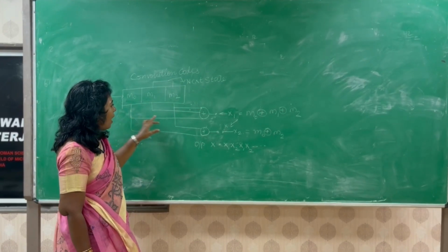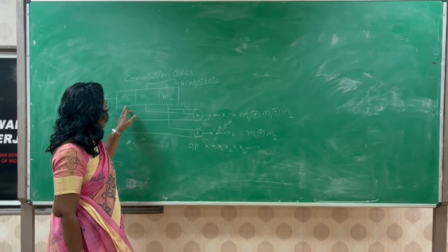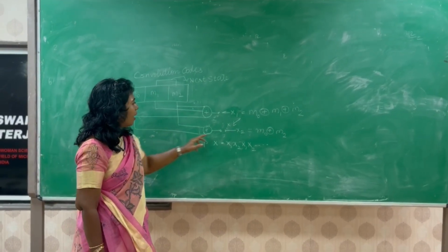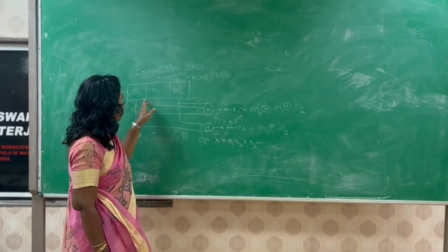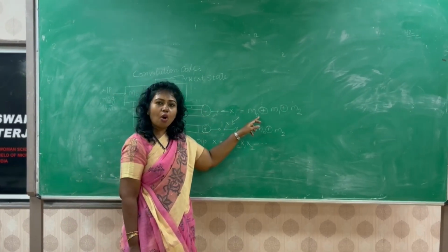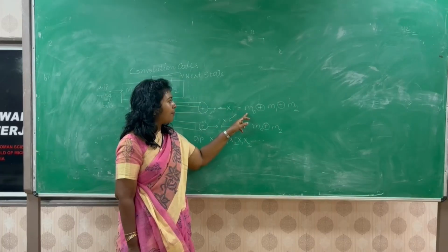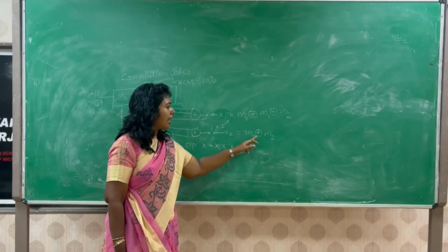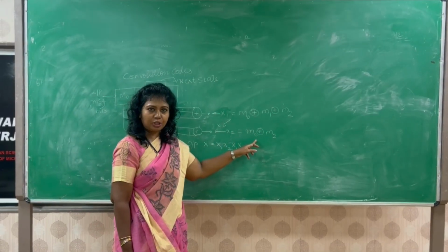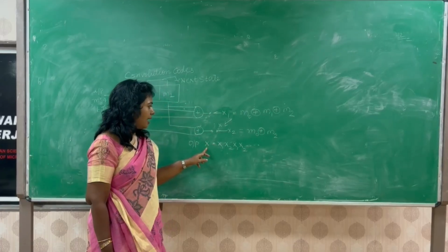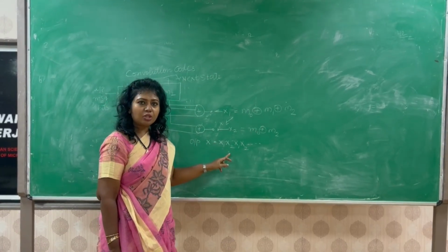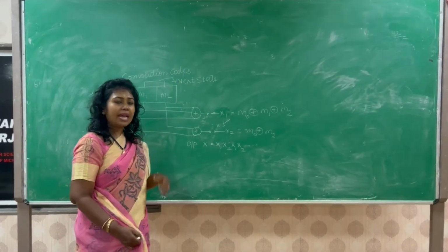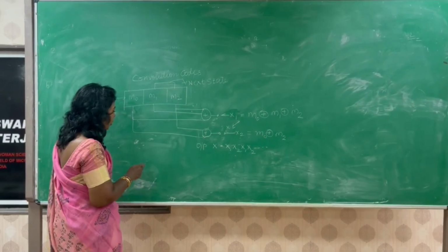Now, we take an output x1 by taking connections from M0, M1, and M2. And output x2 is taken from M0 and M2. We do an XOR operation to get the XOR output of M0, M1, and M2 registers. X2 is the output of M0 and M2 registers with an XOR operation. And the final output X is switching between x1, x2, x1, x2.